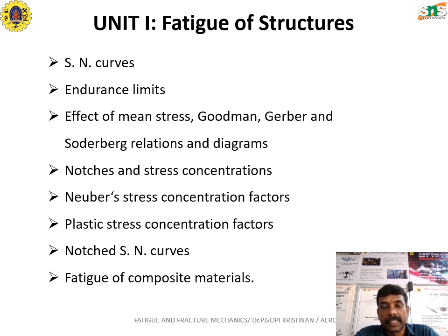It starts with the SN curves, that is stress with respect to the number of cycles curve, especially for the fatigue testing. Endurance limits we will be discussing, and there are going to be three relations with respect to the testing of fatigue and the prediction of the fatigue strength for the given component. That will be explained later, which are named Goodman, Gerber, and Soderberg relations.